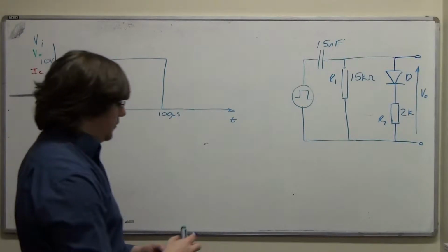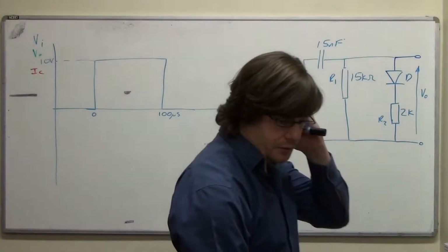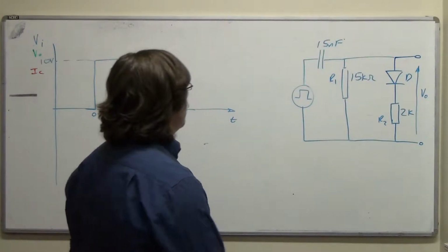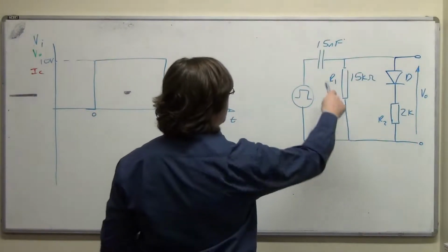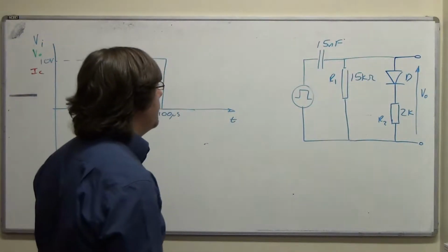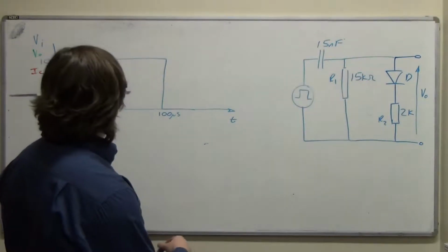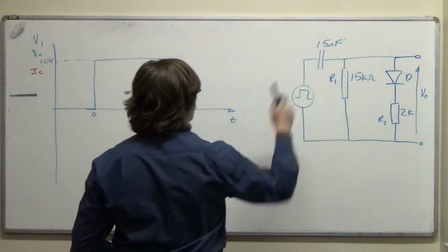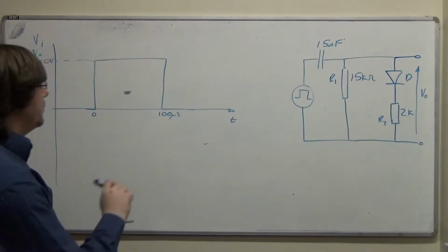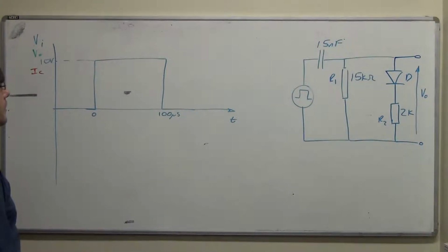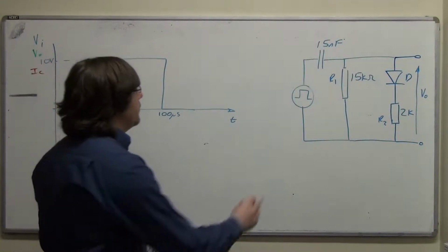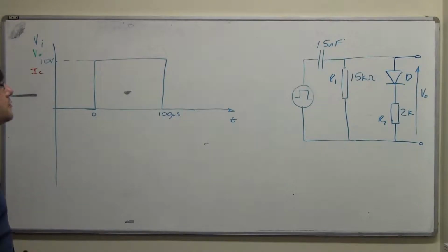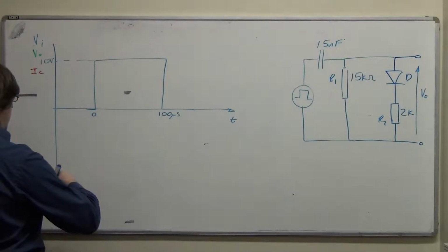Okay, so this is the first circuit on this tutorial sheet, which is actually high pass. So we've got the capacitor now in series instead of in parallel with the output voltage. So initially, as the pulse reaches the right hand plate of the capacitor, it will pass through, and the voltage V out will suddenly jump to 10 volts.